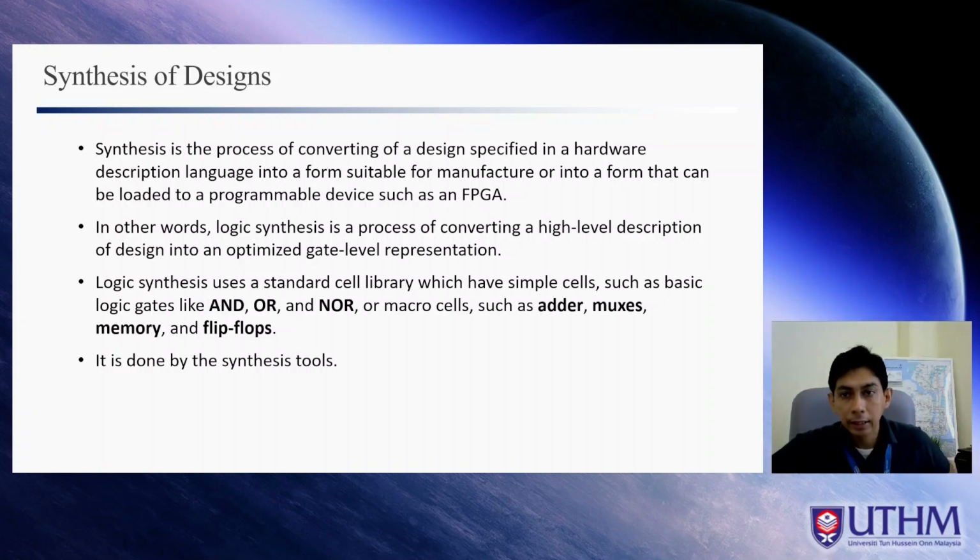All right. Next, we will go to the synthesis of design. Synthesis means the process of converting the design specified in the hardware description language, meaning your code in Verilog, into a form suitable for manufacture, or into a form that can be loaded to a programmable device such as an FPGA. So it depends on what the target technology is that you want to use.